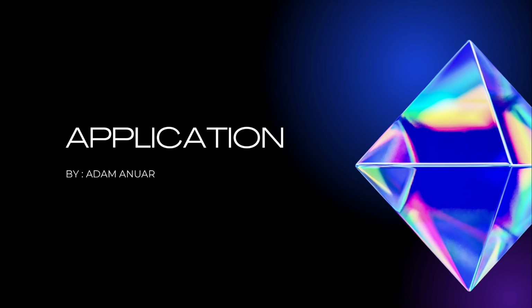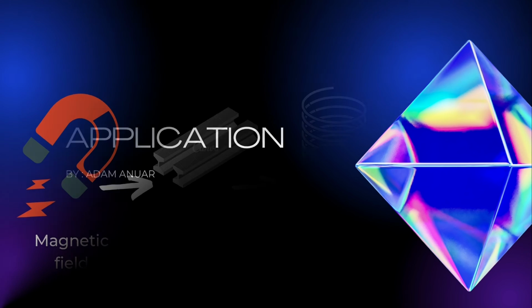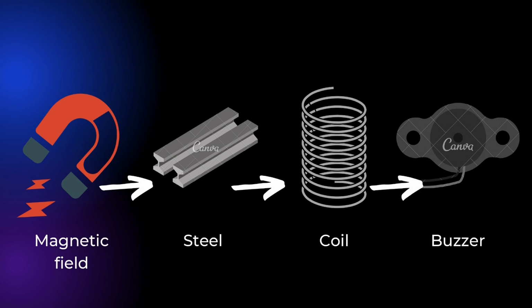Next, I will describe the application of coil electromagnetism and how it works to detect metals. The magnetic field makes an electric current flow inside a metal object. This flowing electric current creates another magnetic field around the object. The magnetic field cuts the receiver coil and moves on it. The magnetic field makes electricity flow around the receiver coil and up into the receiver circuit at the top, making a buzzer sound that informs us we have found something.